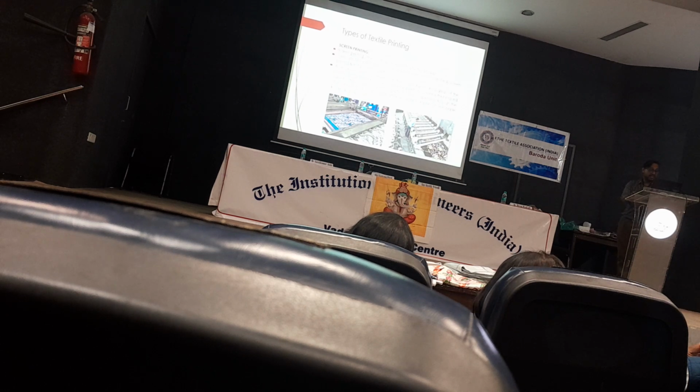And then screen printing. Screen printing is the most common printing method today. There are two basic types of screen printing, flat bed and rotary. A design is created in reverse on the screen by blocking areas of the screen with a material such as an opaque print. The screen is then placed over the fabric and the print paste is forced through by a squeegee, made of rubber or some other material, a flexible synthetic rubber and steel blade, known as squeezing.